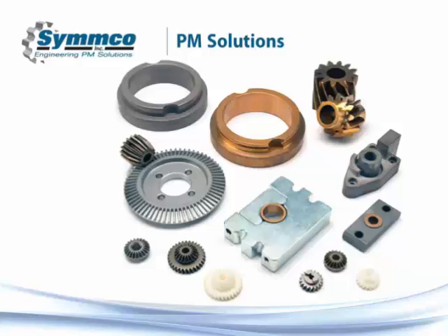Now, and again, I want to be careful here: at no time should anyone producing powder metal parts say they can exceed the dynamics of a wrought material, regardless of what have you. So we do adequately describe that in that MPIF standard to make sure that you know, while we can achieve those HRC 60 hardnesses, we don't want to deceive anyone into thinking that we exceed wrought properties. That would be wrong of any powder metal parts supplier.